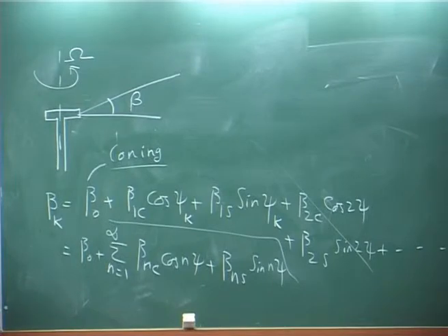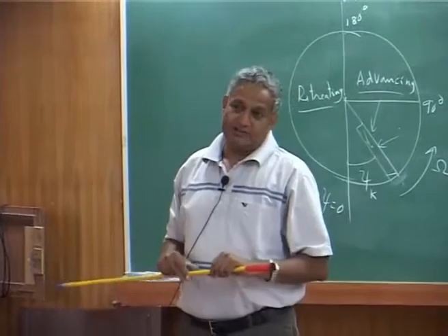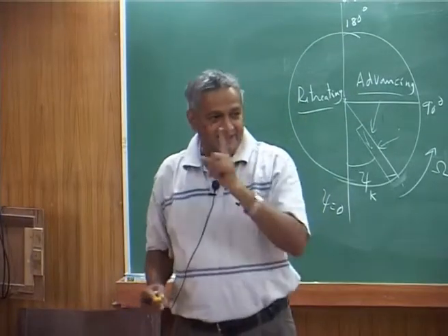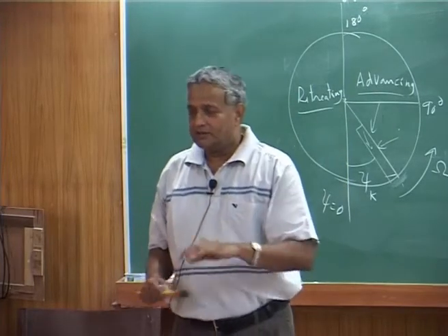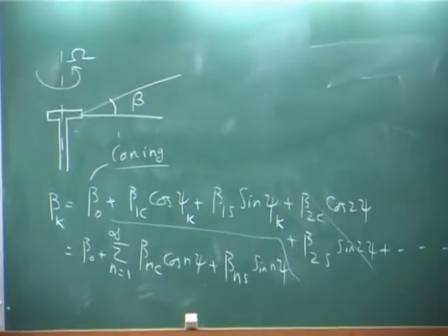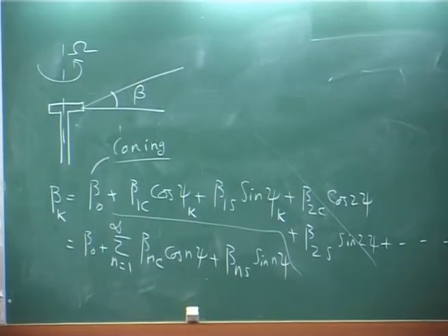But when you do cyclic, swash plate cyclic pitch, because the pilot sticks left side or front, he is basically tilting the swash plate, as a result he is giving a cyclic variation in the pitch angle, okay. The cyclic variation of the pitch angle is responsible for tilting the disc, because one side increases more lift, other side less, so it kind of tilts.